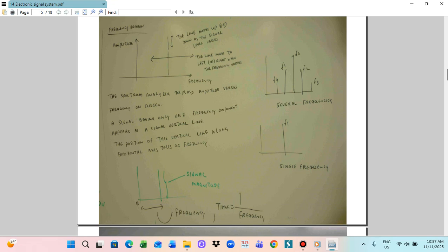So the frequency analyzer is different from the oscilloscope. On oscilloscopes, waveforms are usually shown, so you can see whether your waveform is sinusoidal, square wave or sawtooth wave. But the frequency analyzer does not concern itself with the kind of waveform, only the frequency. So the frequency magnitude is the vertical line, the distance from the zero axis to the point on the vertical line is the frequency magnitude. The X-axis is a scale relative to frequency, like 1 mega, 3 mega, 100 mega.